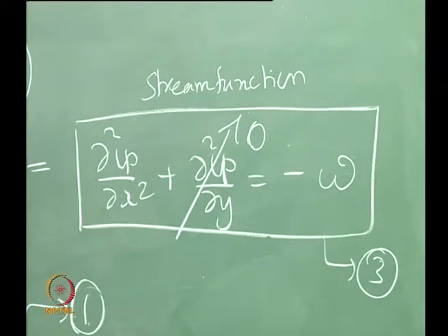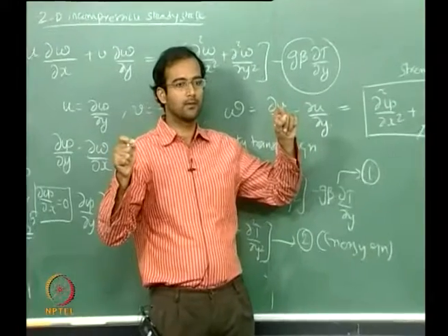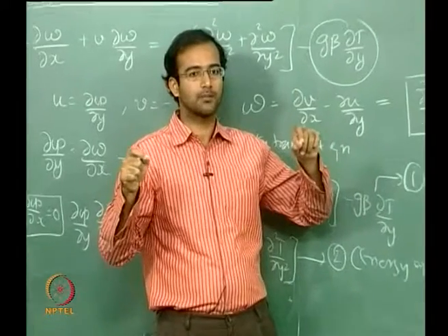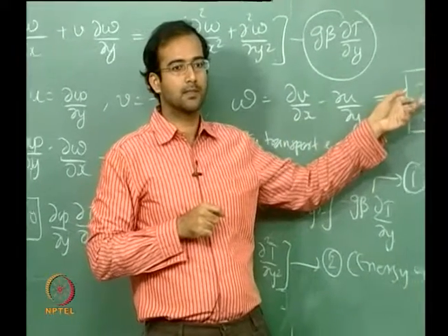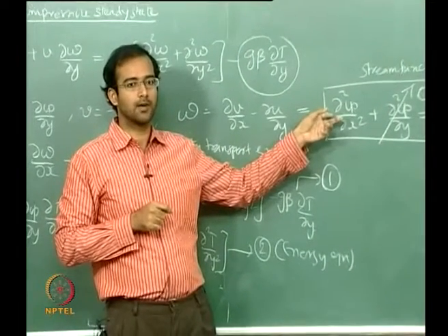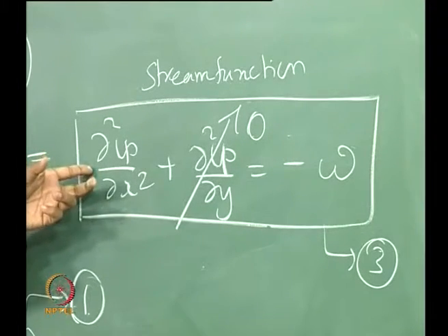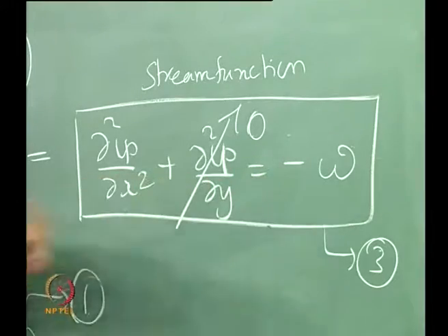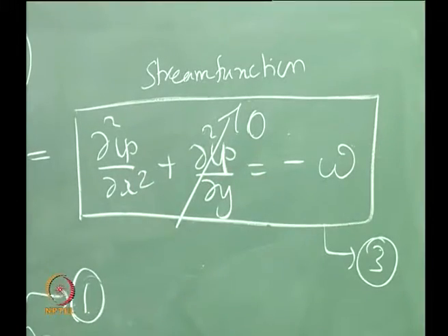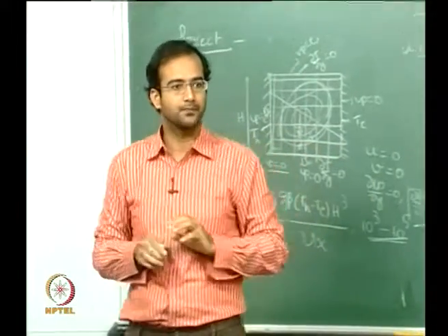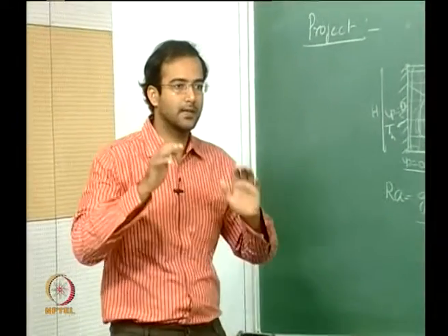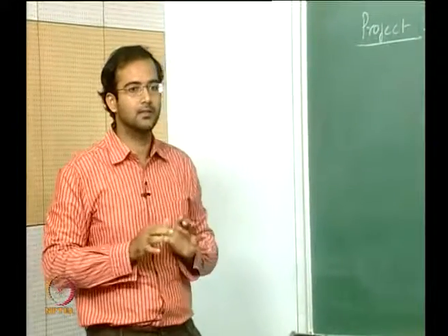You can write this as a simple Taylor series expression for the boundary in terms of the interior point, and you can express this in terms of the stream function at the boundary. So therefore you can directly calculate your vorticity at the boundaries. All this is very clearly explained in the document. So please read through the document. If you have any questions, you can ask me.